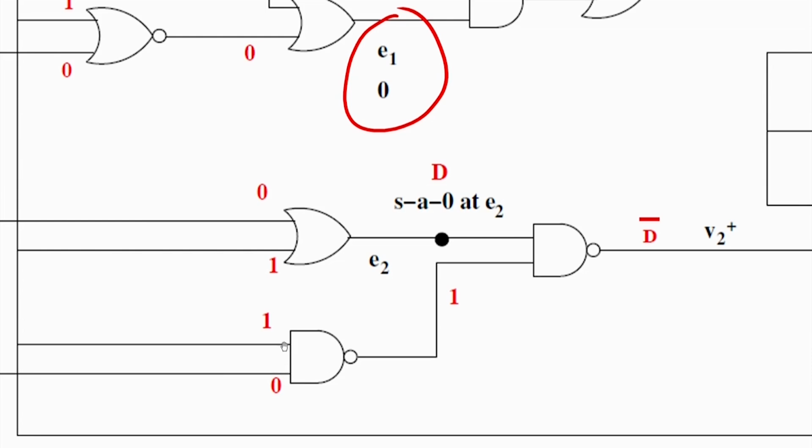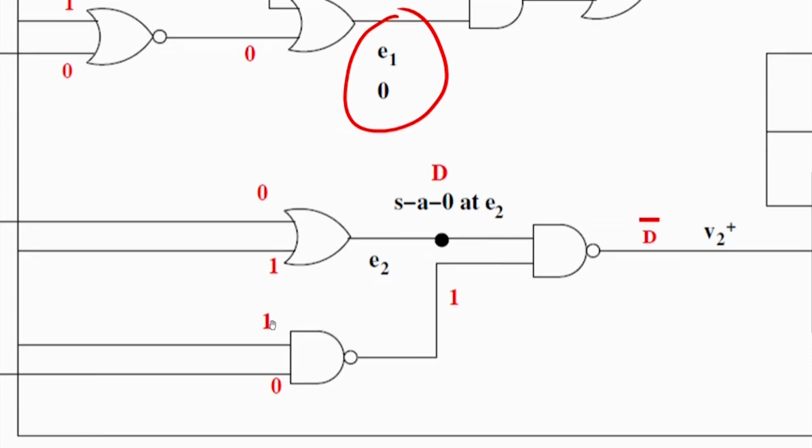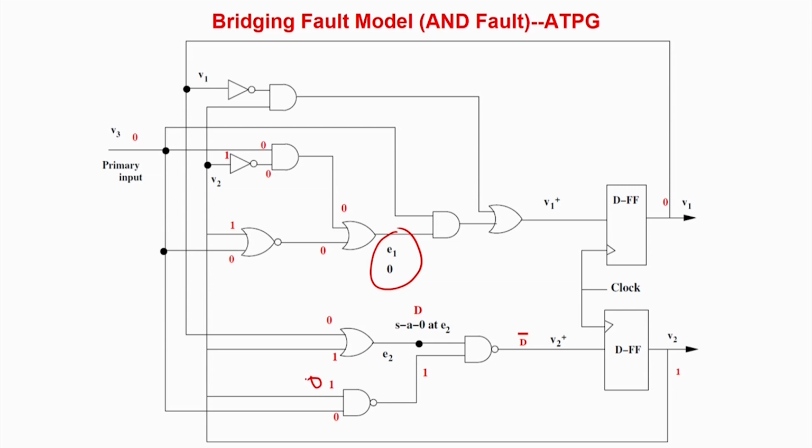Basically you see, you can have a 0 over here. It's possible because 0, 0 is also going to give you a 1. And as I told you, you can also have a 1, because 1, 0 and 1, 1 can both give a 1 at the output of the OR gate, that is at E2. But now if you take a 1 over here and a 0 over here, as this is the same line, there will be a conflict. So there will be an issue. You can see there are a lot of conflicts over here, so then you have to reiterate. This is standard reiteration.